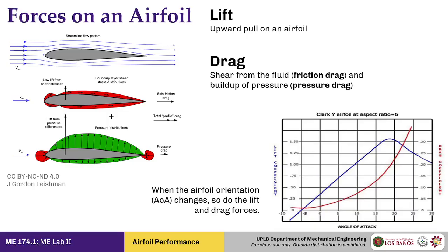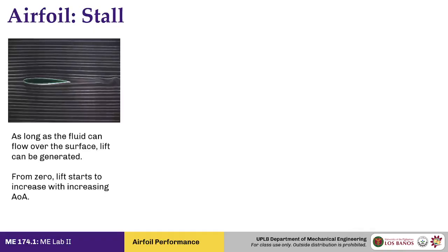Now, alright, so why does lift not behave in a similar way to drag? That is because lift is generated mostly through contact of the fluid over the airfoil. So when the fluid separates from the surface, that surface no longer experiences any of that suction pressure that you would otherwise see when the fluid is attached.